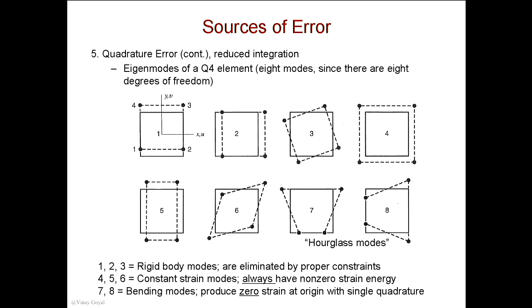Same here. If I'm this quadrature point here, I can also sense movement here, I can sense movement there, I can sense movement there. So a single quadrature point is going to pick up this behavior very well, which is basically stretching. Now, if I'm a point here, it's also going to see that I have shearing going on, because I see a change in angle there, there, there, and there. So that single quadrature point can actually pick up deformations 4, 5, and 6 very well.